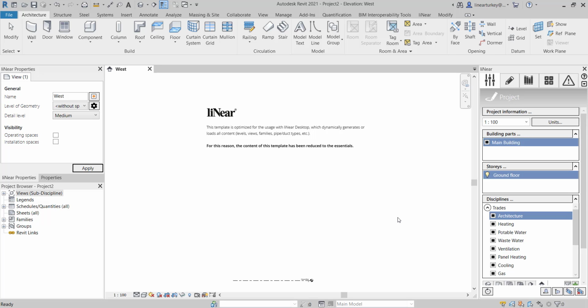First of all, if you do the planning in Revit, liNear will transfer all cooling loads automatically from Revit to liNear Building. By this means, if you have a Revit project that has all of its loads implemented, you can have the results in no time. Now we will see how to detect a Revit project with liNear Building Analyse.